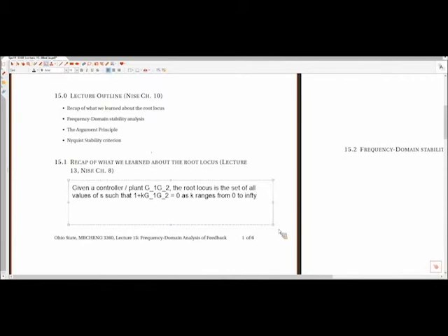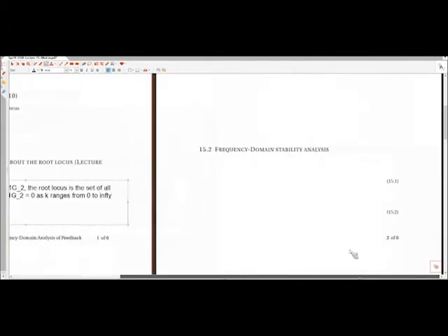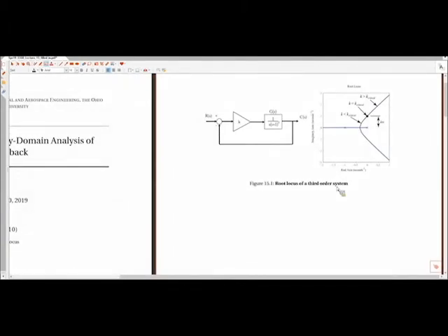And so what this means here is if I have some sort of system, this is just a dumb example, my controller and my plant, I can lump into G of S. This would be G1, G2. I would have this structure here, and I would look at my root locus plot, and I could understand stability, and I would say that I have marginal stability when this K is equal to this K critical. In this range, I am stable, and in this range, I am unstable.